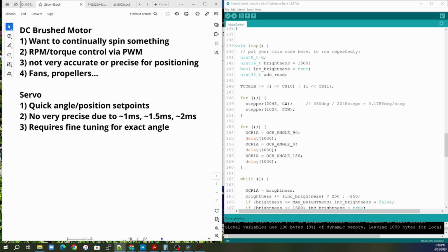Like on this one, you might find that 27 clicks give you what you want, right? And then on the next one, it might be 35, and that's just coming from you not changing a program, just you making a second item using the same servo. So you can have some variation in the servo itself. But it's good for any general angle application where if you're not really too concerned about it, you can use it, right? And finally, the stepper.